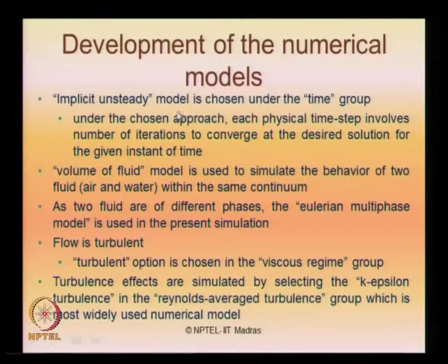Implicit unsteady model is chosen under the time group in Star CCM. Under the chosen approach, each physical time step involves number of iterations to converge to the desired solution. The volume of fluid VOF model is used to simulate the behavior of the two fluids, that is air and water. As two fluids are of different phases, the Eulerian multiphase model is used in the present simulation.